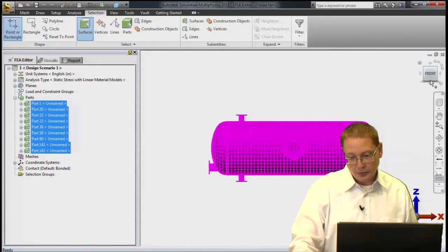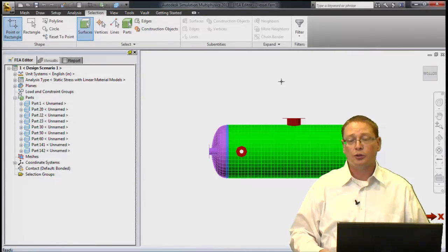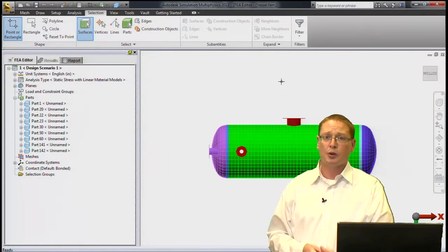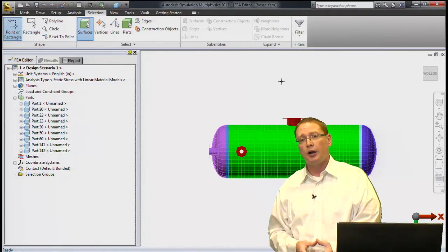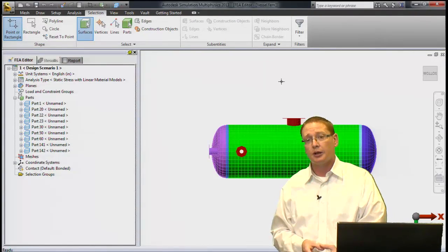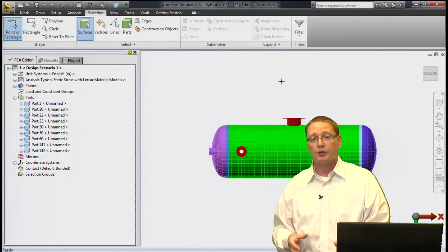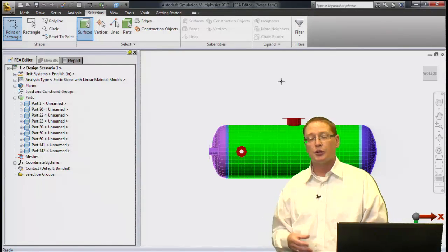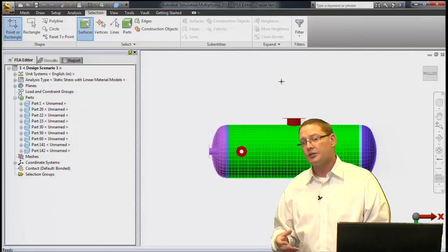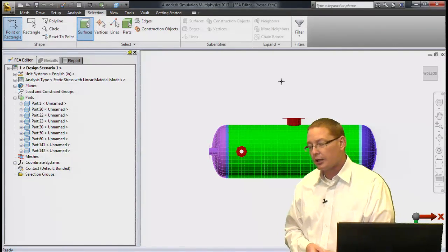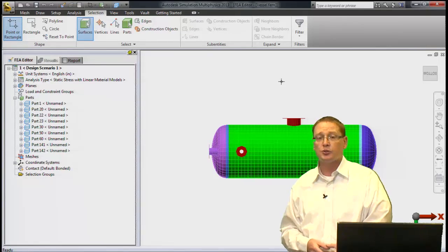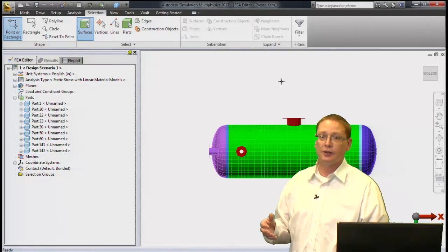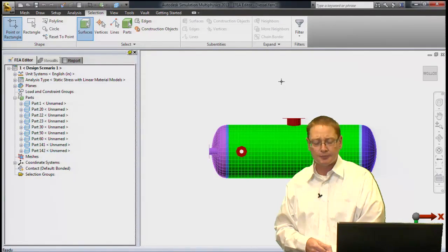Now, what you do with the model next really depends on what you're looking for from the pressure vessel. Of course, we might have considerations for thermal, so we might want to take a look at, when I heat this part up, what does the distribution in the thermal analysis look like? Or maybe I want to see a thermal stress, so I could run a heat transfer analysis on it. Then with this thing at an elevated temperature, how does that expand, contract? What does that do to the stresses in my model? You could take a look at something like a transient thermal, so you could look at a time-dependent analysis and then likewise take that into a mechanical event simulation where you're looking at time-dependent stresses.